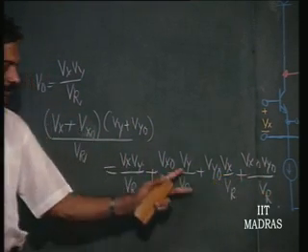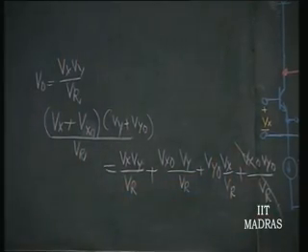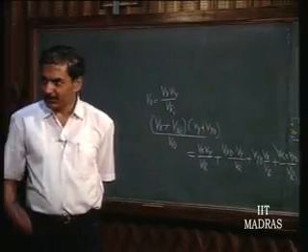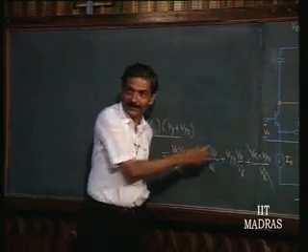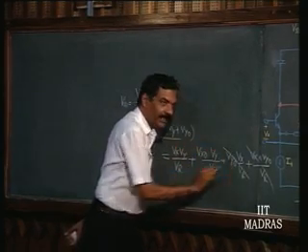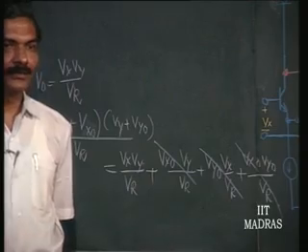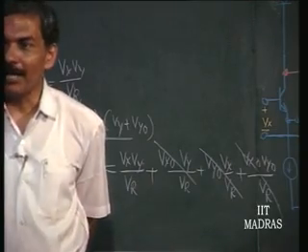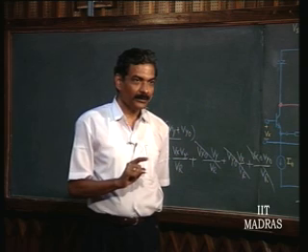So, what should you do? You should subtract DC. Subtracting that DC is not a problem, it is only a DC, and you already have V y and V x with you. Some portion of V x and some portion of V y has to be subtracted from this. Using an op amp, I want you to obtain a generalized what?